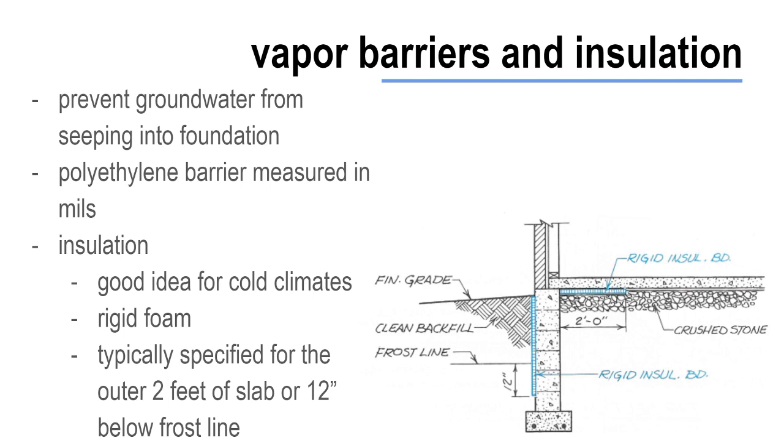Sorry. To help stop water from the ground seeping into our foundation wall or from underneath in our concrete slab, we can use a layer of gravel over the area before we place our concrete. That way I don't have earth directly touching this concrete slab. There's just crushed stone or gravel underneath it.